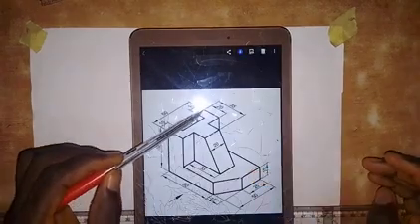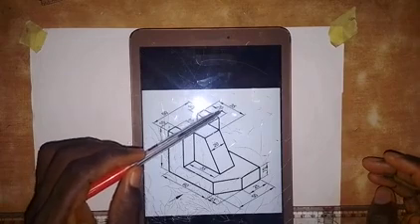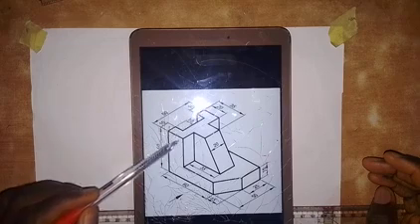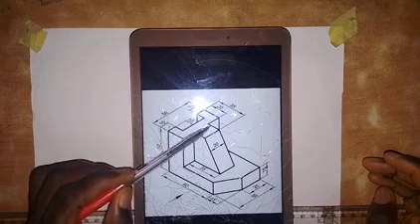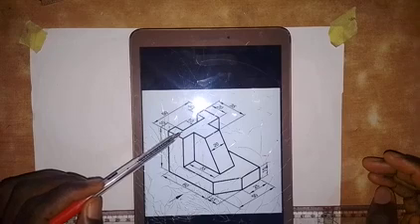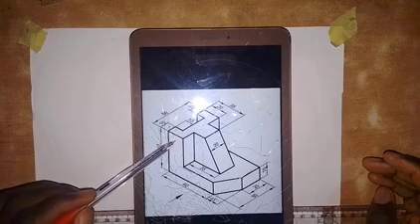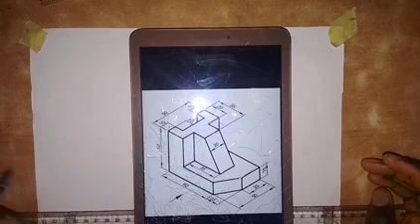And the total from here to this end here is 35 millimeters. So this is 20 millimeters, as we have here 20 millimeters. And then the balance from here to here is 15 millimeters. And then for us to get a line that will be hidden from us on this face, we take 10 millimeters inward. So that is what we have to do.